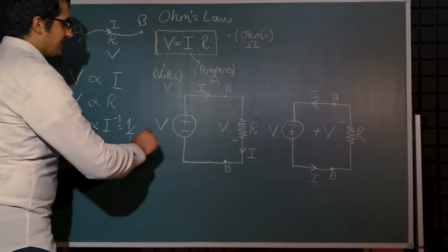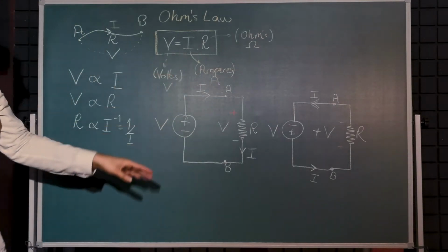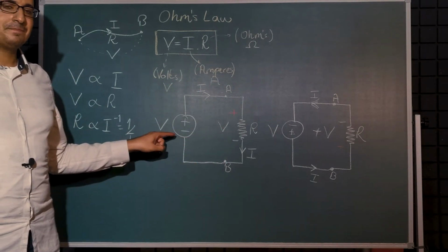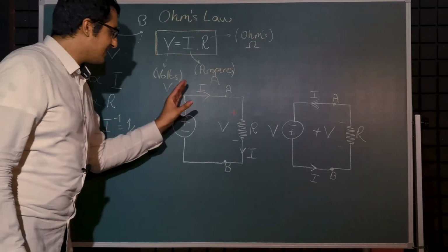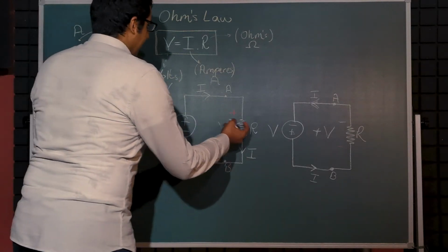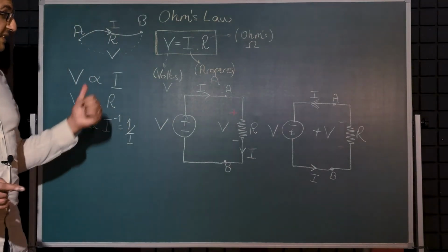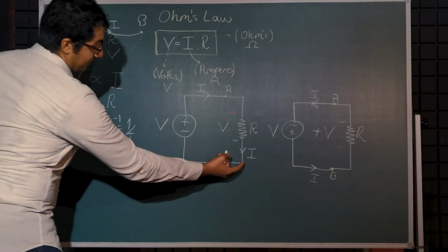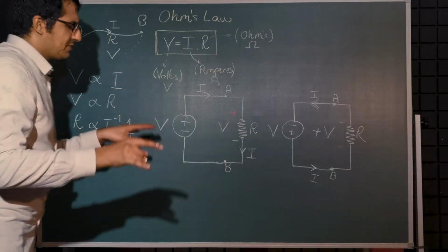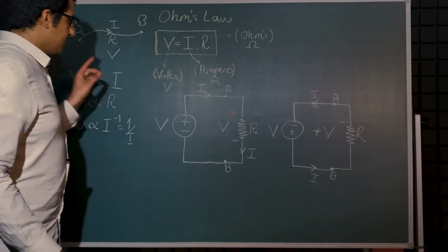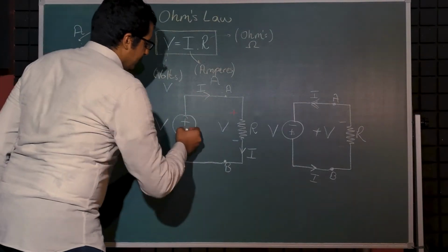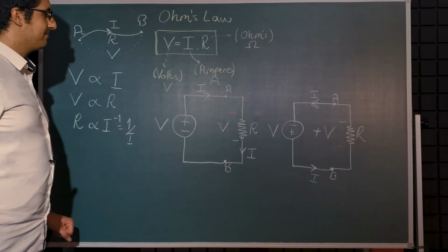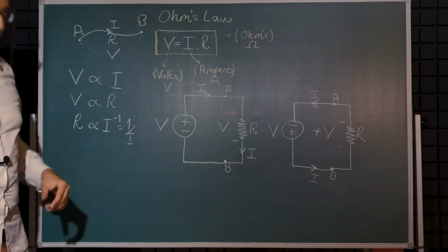But you should bear in mind that current will exit the positive terminal and then re-enter the source from the negative terminal. This is something inverted, related to electrons, because since electrons have negative charge, electrons will always leave the minus terminal. But just don't let this confuse you, you always take the current in the opposite direction to electron flow. This is a convention. And this law is called Ohm's law.